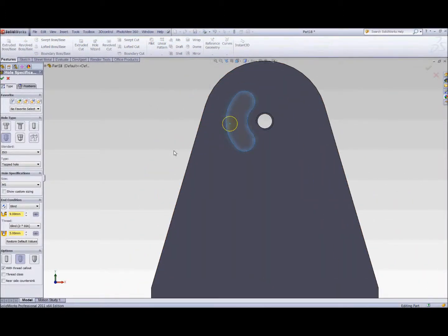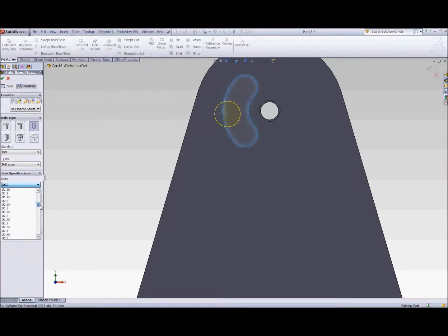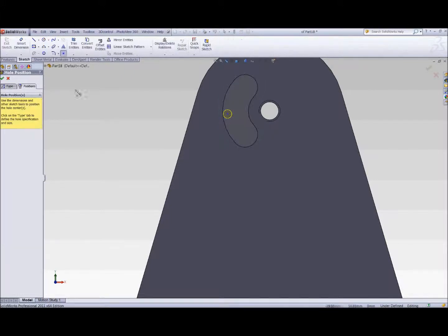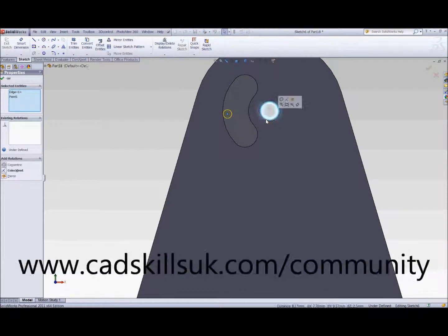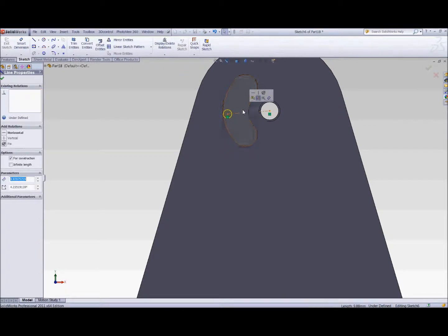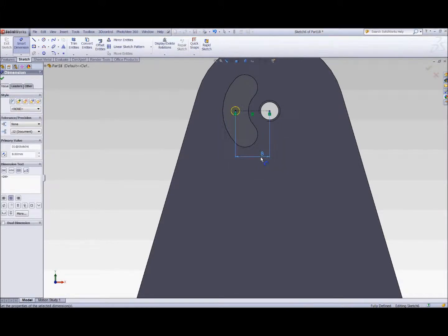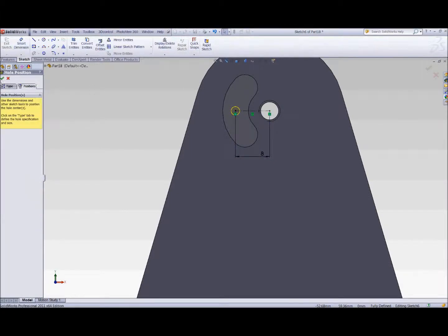Normal to. We have a hole in this position which is 2 millimeters, 5 deep. So standard hole, 2 millimeters, 5 millimeters deep. Position wise, again horizontal. It's not going to allow us to pick it straight away. What we can do is use the technique we've used before, just to sketch a center line and constrain that horizontal. It's on a 16 PCD, so I can go there to there, 8 millimeters, and accept.